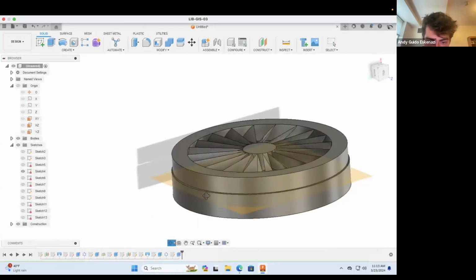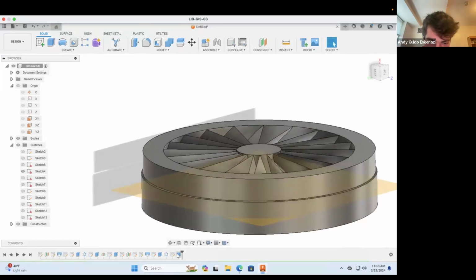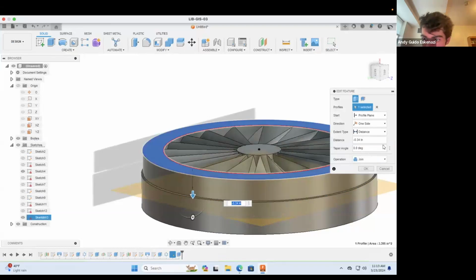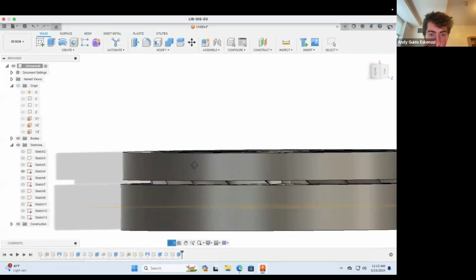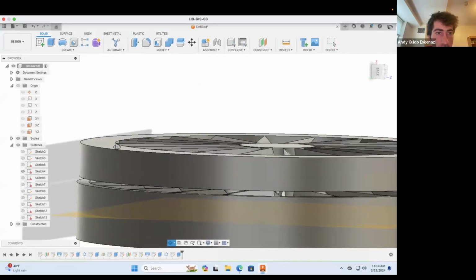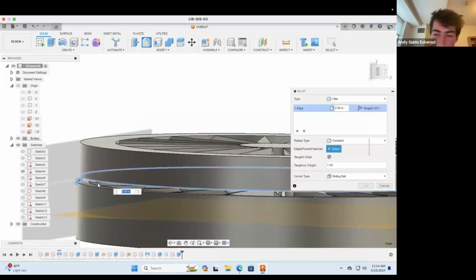The way there is a little bit of a gap, maybe what I'm gonna do is feature, maybe that way it's more noticeable. There, just like that. So what am I gonna do with this? The following thing. First thing, I'm gonna fillet that edge by, let's see, 0.2.